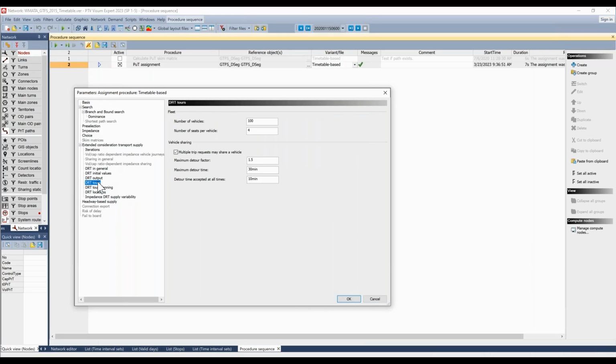All right, and so it looks like there's also a question for headway-based assignment. You showed a slide indicating that crowding was a factor in route choice. Can you explain more about how it differs from the discovered hard capacity constraints in the schedule-based? The answer to that is the headway-based discomfort factor is applied basically as a penalty or shadow price, so that gets factored into the overall impedance during the assignment. So that is in contrast to the timetable assignment, which allows either hard constraints or the shadow pricing method.